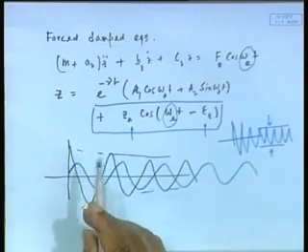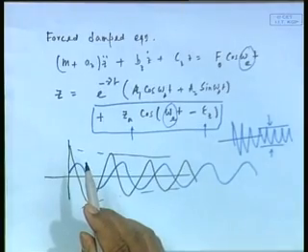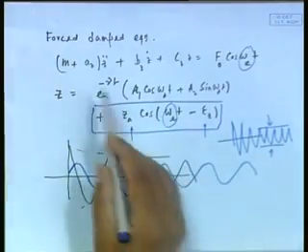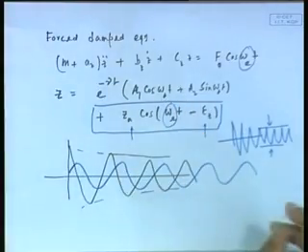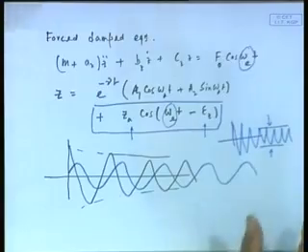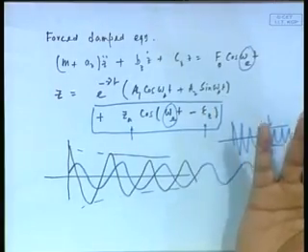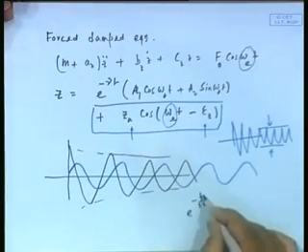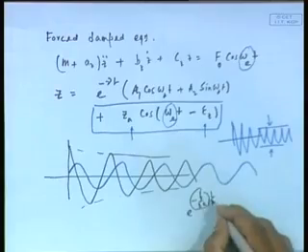Yes. So, that assumption that t will be very large is true for maybe an offshore structure? No, not at all. It has nothing to do with structures here. When we are talking about a ship, the whole period might not be that long. This is a decay factor, minus b by 2a. This makes the exponential small. In real life, within just 1 minute it will become 0, because you are having e power of minus b by 2a times t. If you give t 1 second, 2 seconds etc., very shortly it becomes practically 0. In reality you won't even notice it, it will be almost 0 in like 3-4 periods, 10 or 15 seconds or so.